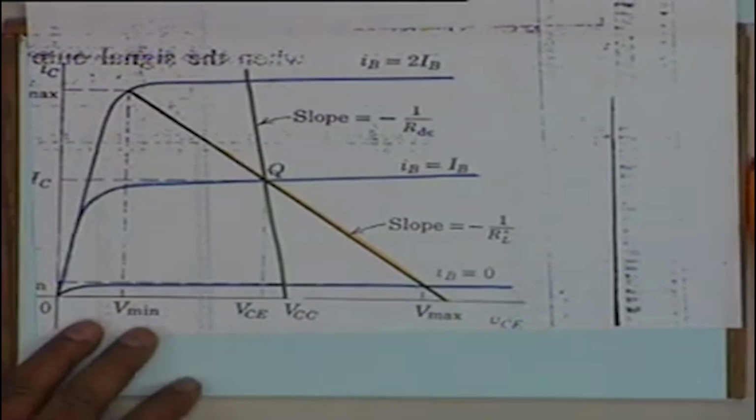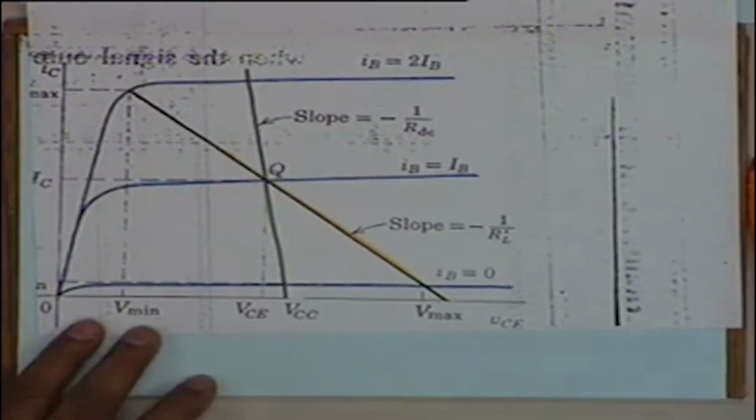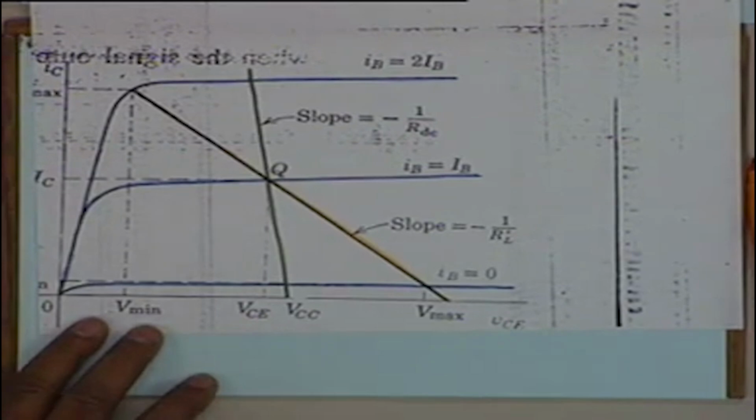All right, and there are several things now which one has to be very careful about. You see, in the transformer coupled amplifier there is no RC. The DC load therefore is simply RE plus the small winding resistance of the transformer. Small means several ohms, and in a power transistor you have seen in the previous case that RE is of the order of 15 ohms.